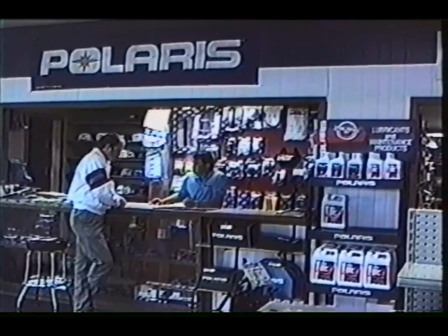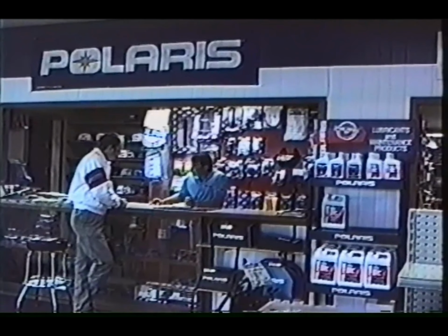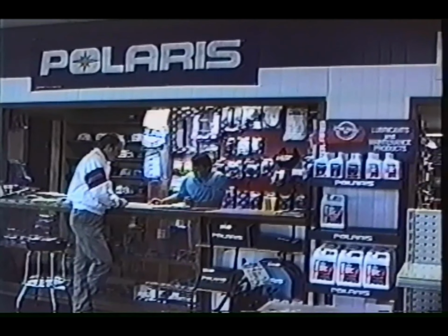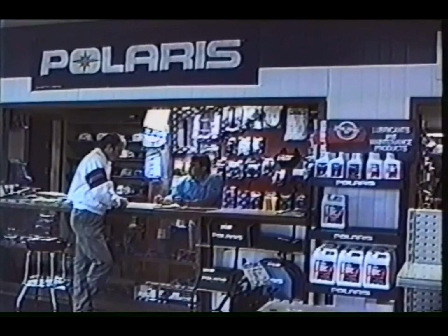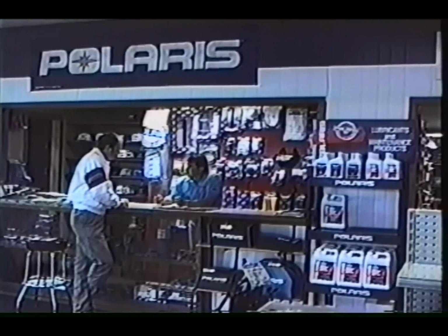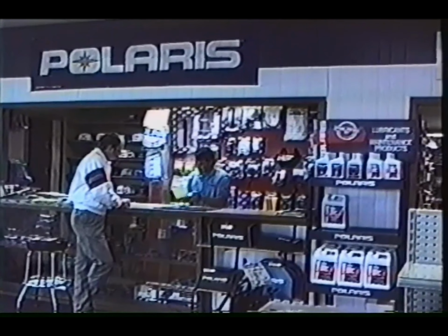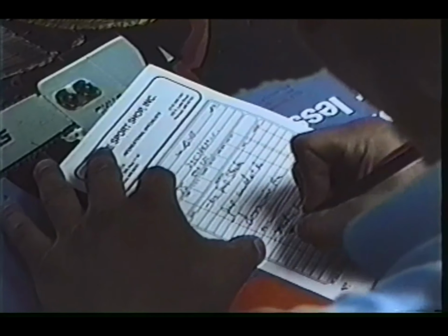Even the most difficult charging system problems can be quickly diagnosed if you follow a step-by-step process. First, be sure to get accurate and complete information from the customer. Ask questions that will help the technician narrow down the source of the problem. Questions like, when did the problem first occur? What type of riding does your customer do? Was the vehicle in storage? Was it a sudden problem, or did it occur gradually over time?